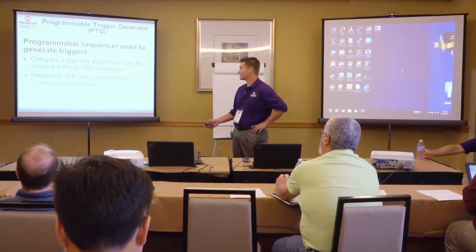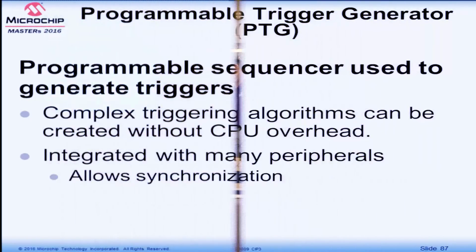We'll start with the PTG. So, I know it's 2 o'clock and it might be a little sleepy, so we're going to go through the super exciting programmable trigger generator. So I'm sure everyone will just be excited. So what is that? It's a sequencer that's used to generate triggers. It allows you to make some more complex triggering algorithms without using the CPU itself. It's integrated with some of the other peripherals.